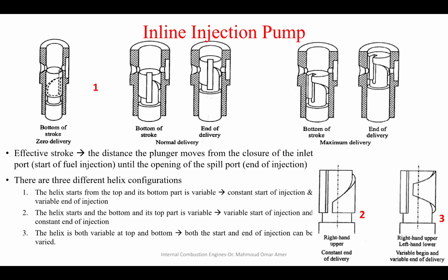Which one will close the return port first? The first one will close the return port first. When it closes the return port, what will start? The injection. So the first helix will be the first one to start the injection.